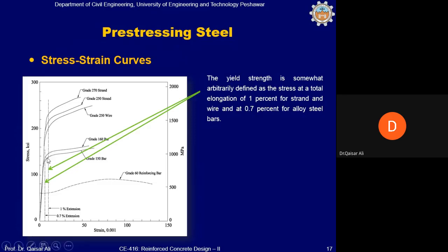It is important to note that the exact determination of the yield strength is very important, because if the steel wires or cables are stretched even close to the yield strength, there is a possibility that they permanently set, and permanent setting will then give us no stretching. So it is important to calculate the yield strength very accurately.